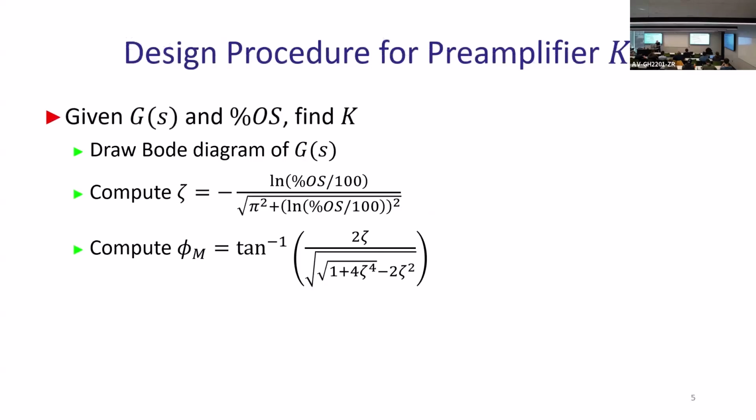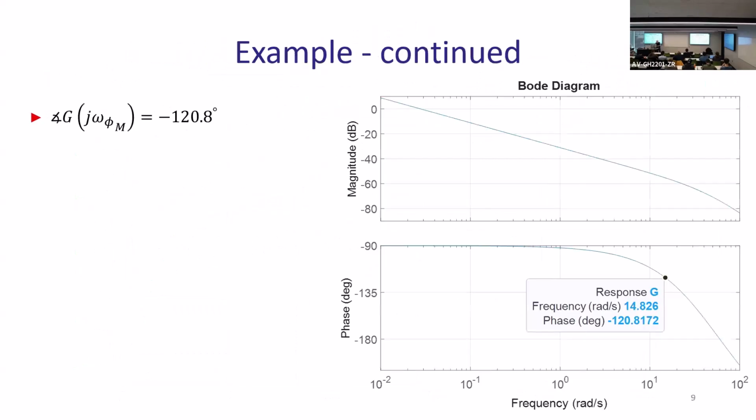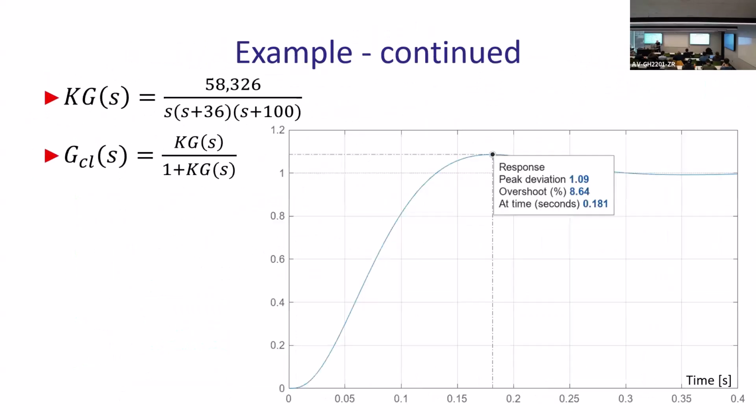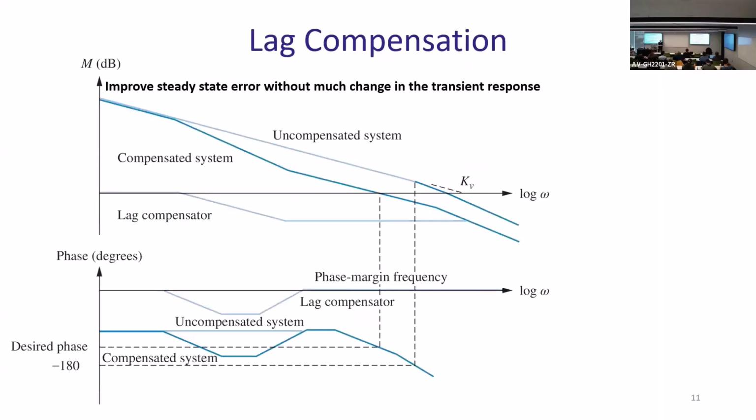Now, the idea for the second one, which is second, we'll get to it here. Okay, lag compensator was saying something very, very similar. But the problem with K, the regular K without lag compensator, is that you're shifting entire gain up and down. You cannot shift it by parts. All right, so you cannot shift left part more than right part. It shifts the entire thing. If you add any particular kind of gain, the entire plot goes up or down.